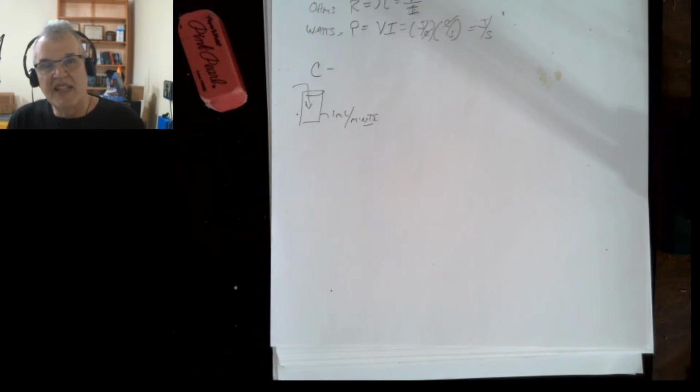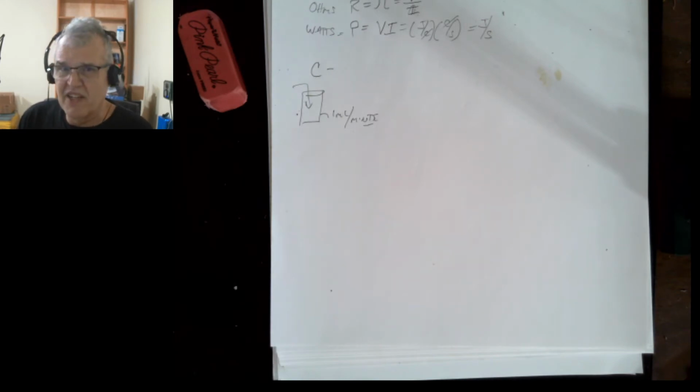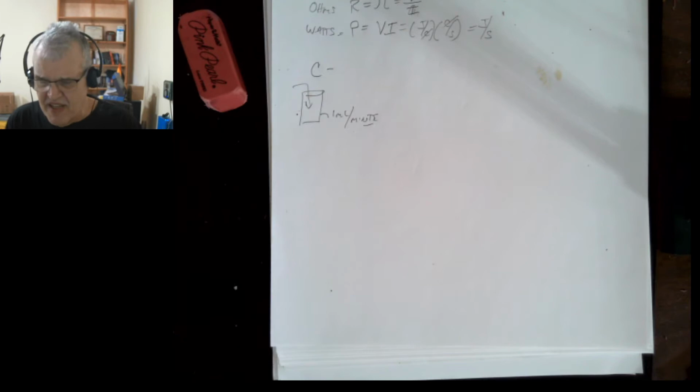And the reason for that is the faster or slower that you charge it. The slower you charge it, the greater the capacity. The faster you charge it or discharge it, the lower the capacity because of internal resistance and things that we'll kind of get into. But I really can't get into the really nitty-gritty of that kind of thing. That's something you'll have to investigate on your own.